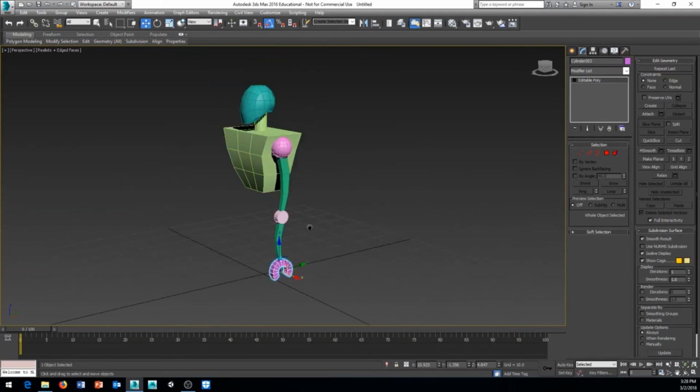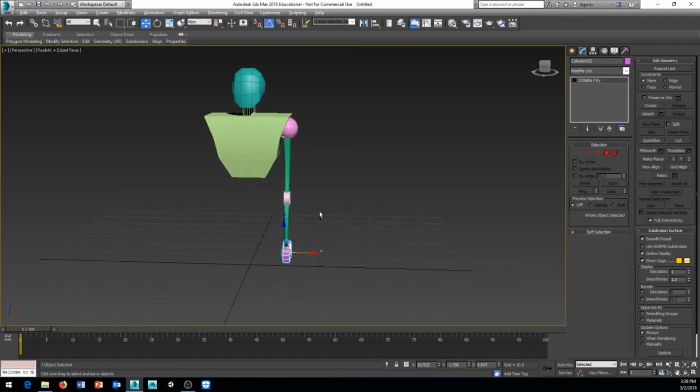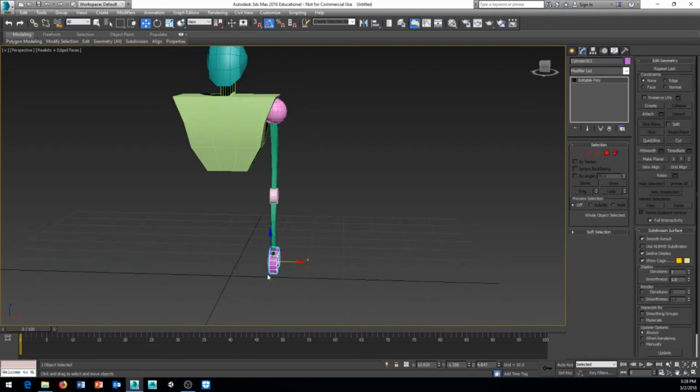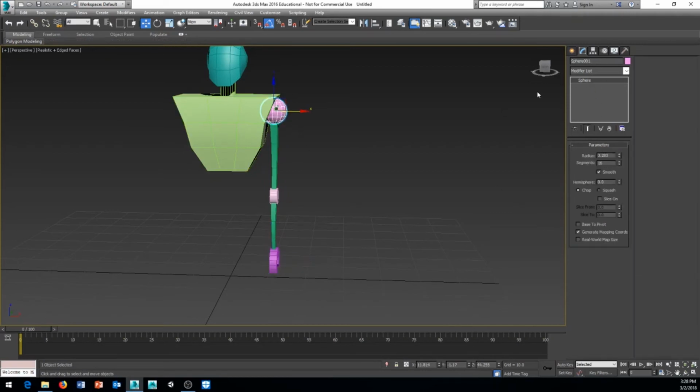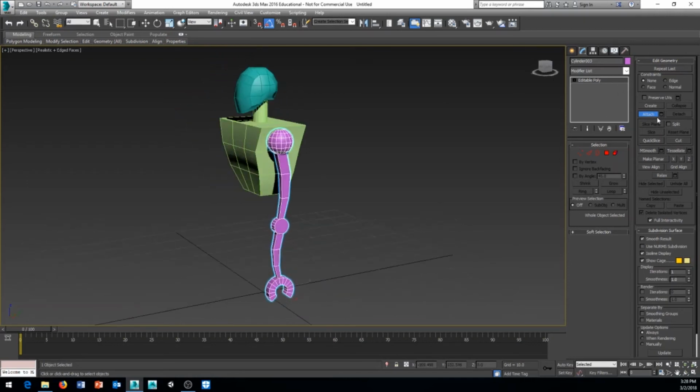Okay, so I have this, and before we talked about that everything was an editable poly, and we did that on purpose, and now I'm going to show you why we did that. There's one feature that we have in editable poly: I can attach other editable poly pieces. So in my edit poly, we have a button called attach. Even if the geometry isn't in Editable Poly, like this is just our standard sphere, I'm going to attach. And now everything that I'm doing here is attached. And again, I want to make sure I name it. So maybe I'll name this left arm.